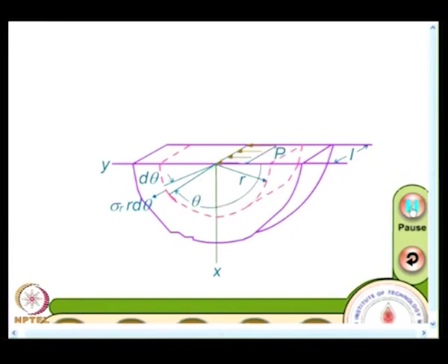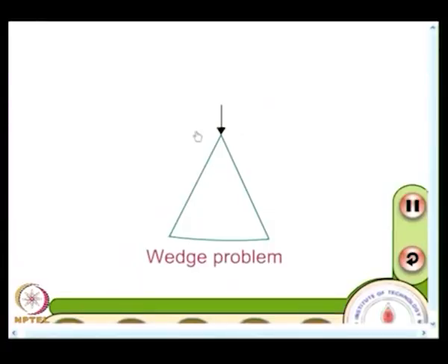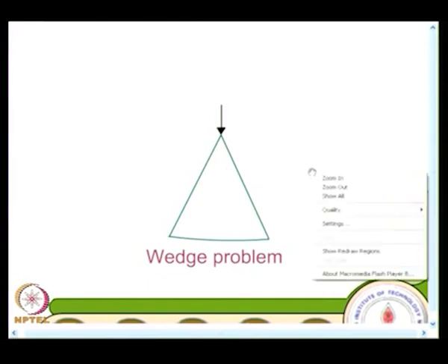and you would also be able to find out for the case of a wedge problem, the same stress function is useful. And where do you find the application of wedge problem? Suppose I want to analyze a cutting tool. The cutting tool is removing metal while you do the machining operation. If you want to analyze the cutting tool, the wedge problem could be invoked. So, from a practical point of view, quite a nice set of problems